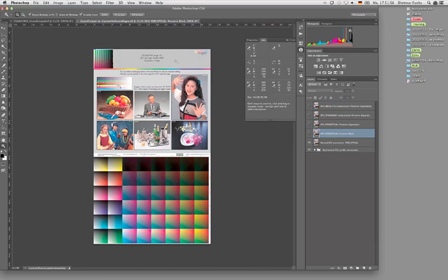So that's the result of my normal ICC conversion. And if I look here into the gray background, you'll see my gray is now 4-color, which is not nice. If I look into this yellow, for example, my yellow has a contamination of a little bit of cyan and magenta in there. This will produce those overprint issues we had in our presentation. Or 100% black, which is this anchor point number 3 here, which is rendered to 4 colors at the end.